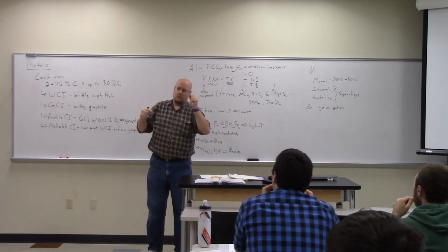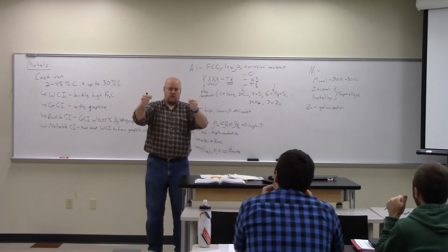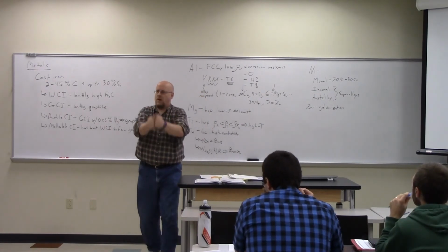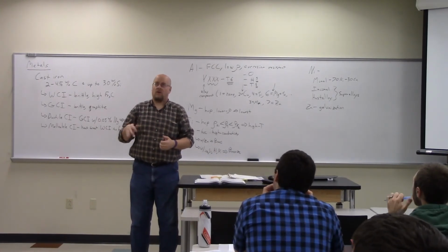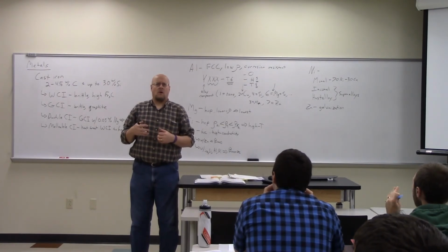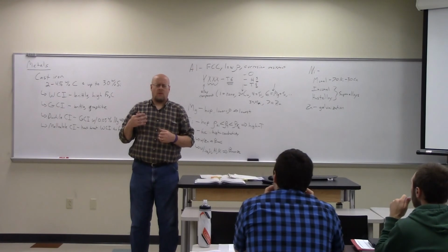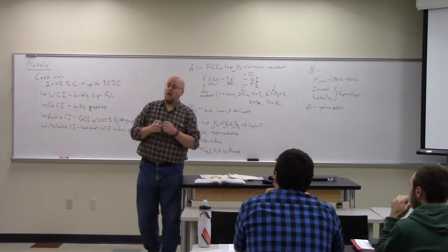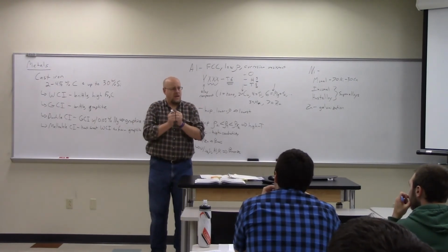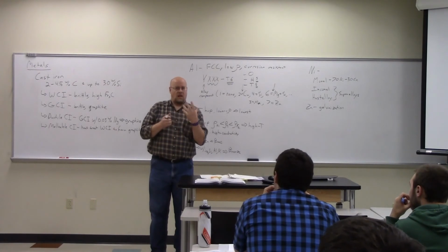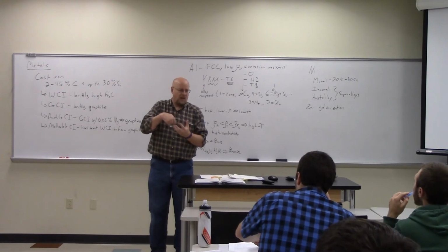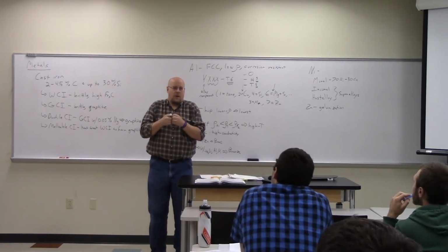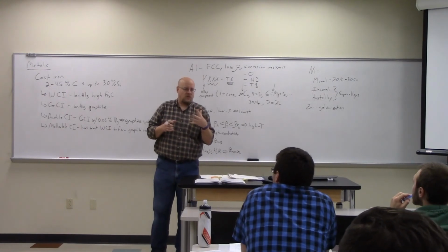So if I put steel and zinc in contact and stick it in a bucket of salt water, the zinc will act as the anode. I always get anode and cathode mixed up. So it'll dissolve and leave the steel unrusted. You form a little galvanic cell, basically a little battery, and the zinc dissolves in deference to the steel.